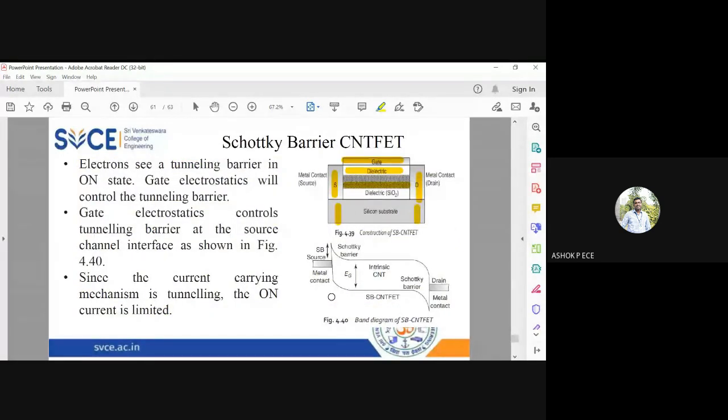But one problem is this. With a silicon-based FET, the advantage is that fabrication is very easy, because I just need to grow a silicon layer between the source and drain. But when you use carbon nanotubes in the channel, you have to fill the complete channel with carbon nanotubes, and then position them in a perfect way.